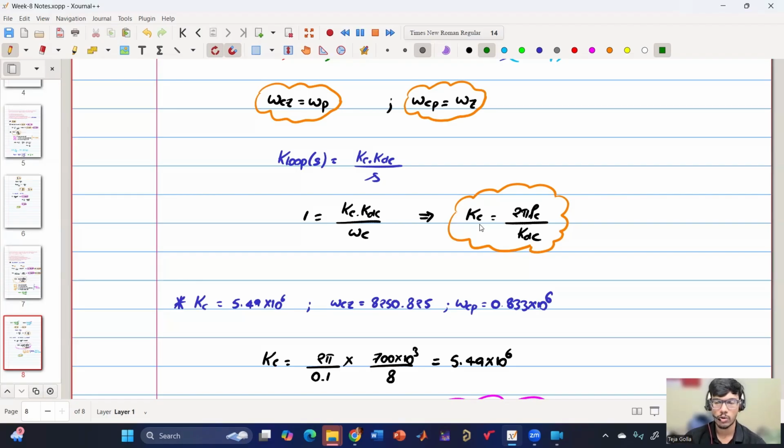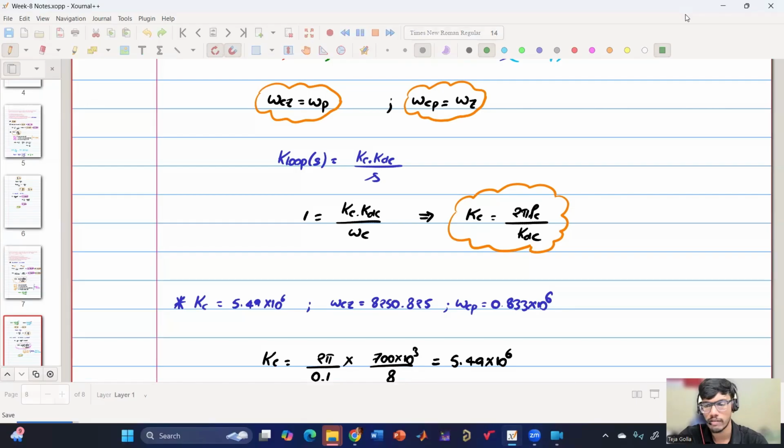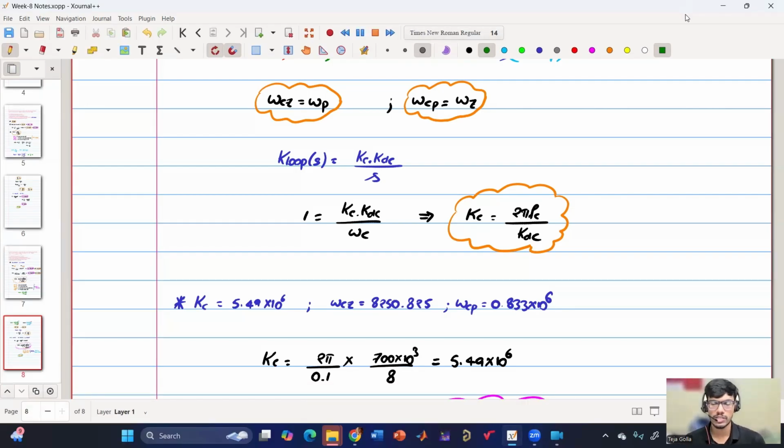The control output, VCon or IC, is basically coming out of an op-amp. In simulation there is no upper and lower limit, but in practical hardware there is an upper as well as a lower limit. That will put a limit on how much gain you have. If you have higher gain, then the reference as well as the control voltage can become a very high value, and then the op-amp might get saturated, which is not considered in the simulation as of now. But yeah, these are the practical issues.